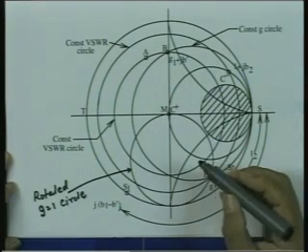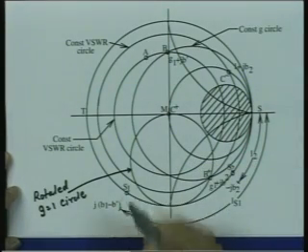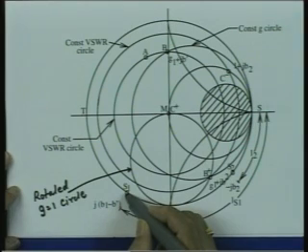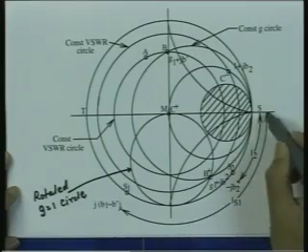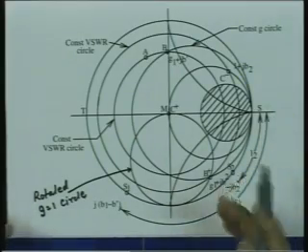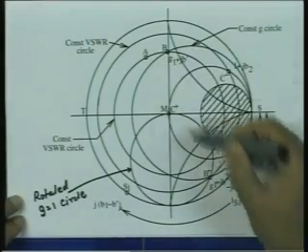I can take this difference, mark it on the Smith chart on the outermost scale, and again measure in the clockwise direction. That should be the length which gives me a susceptance equal to the difference of the susceptances at these two points.